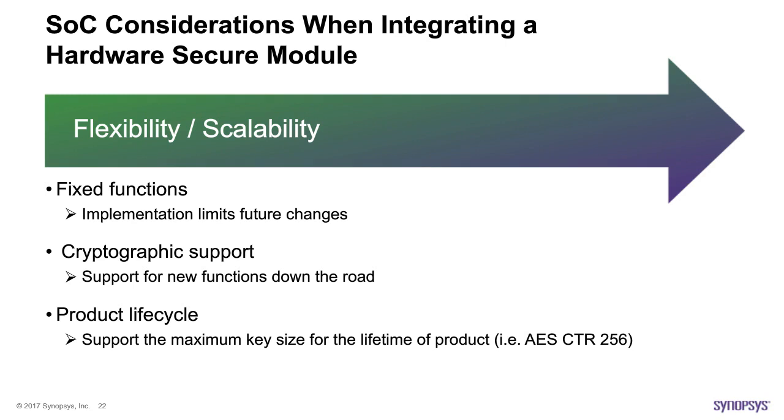It's always good to have some degree of future proofing, as you may never know your customer needs or even your customer's customer needs. So when considering a hardware secure module, review your functions and understand what the upper limits of those functions can be. Understand what kind of expansion you need when it comes to cryptographic support. Also understand what kind of product lifecycle you expect your SoC to go through.